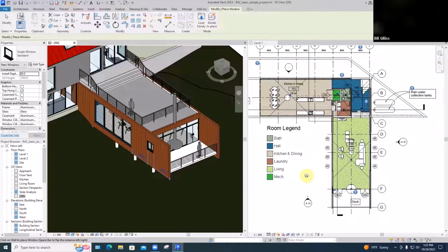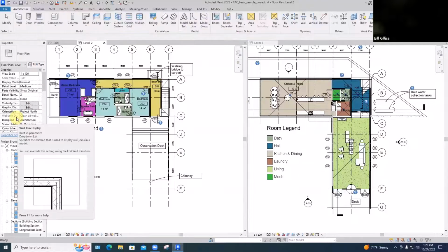There are no layers in Revit. In AutoCAD, I like to use the layer called A-wall for my walls. Somebody else might like A-wall- and then some masonry or something or other else. Other people might just say wall, other people might say W. There's no consistency throughout AutoCAD unless it's enforced by you or enforced by your office. The people who put Revit together decided that's totally bogus. There's no way that different firms or even different people in the same firm can share information.